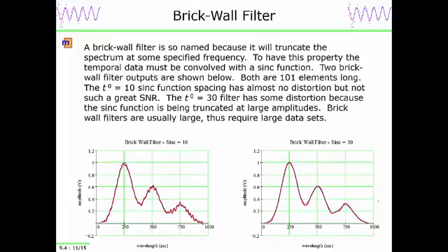And the goal for the digital filters that are illustrated in the lecture notes, there's two of them: increase signal to noise, minimize distortion. You can never do both perfectly, because there's always frequency content of your signal that overlaps with the frequency content of your noise. And if you remove all of the frequency content of your noise at that frequency, you're also removing content of your signal at that frequency. So that's where this striking a balance comes in.